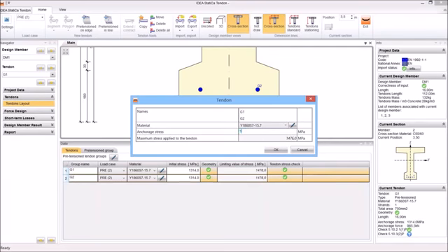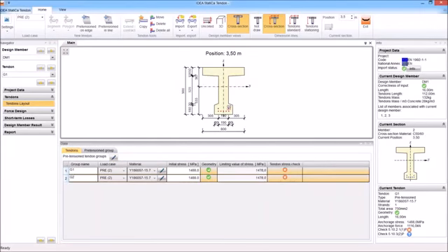By the way, you can see now that we have all the tendon checks satisfactory. But if I go to 148, this high stress, it is bigger than the maximum, as the program gives you 1476. Then we see the tendon stress check is not satisfactory. But I will explain it later, or I will improve it later.